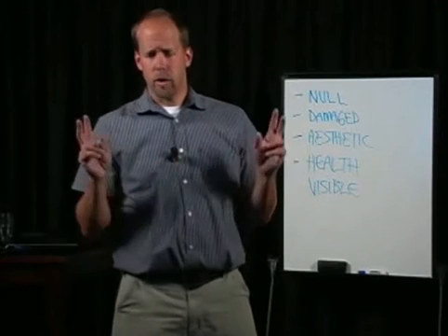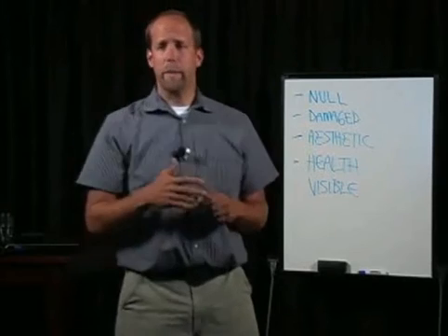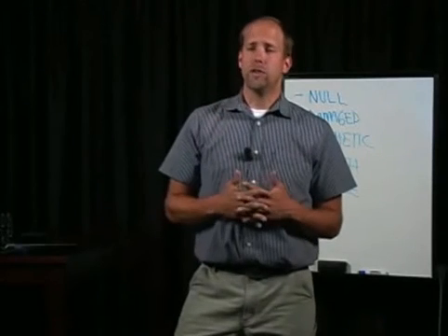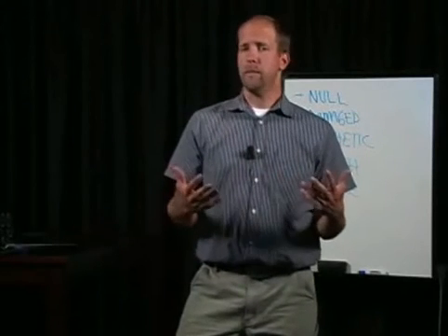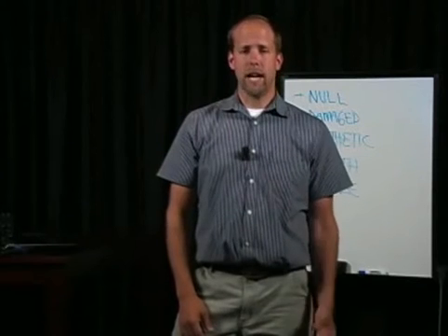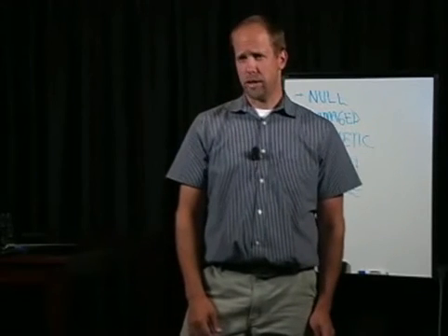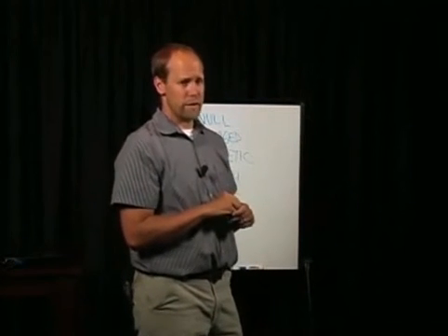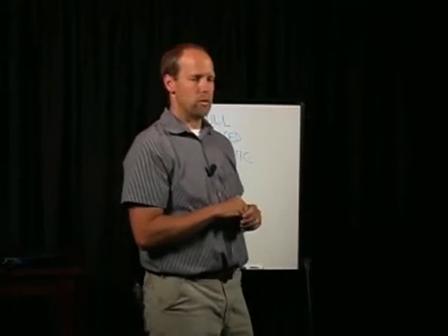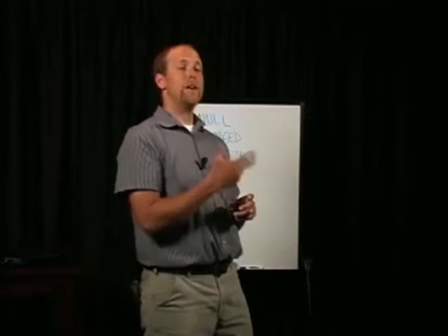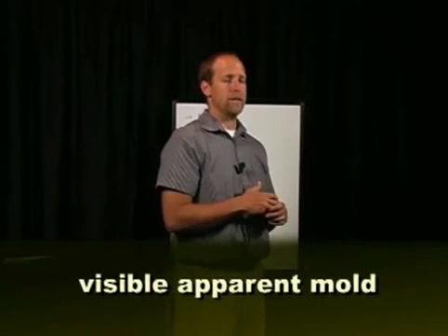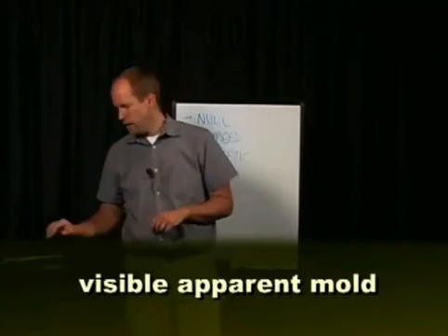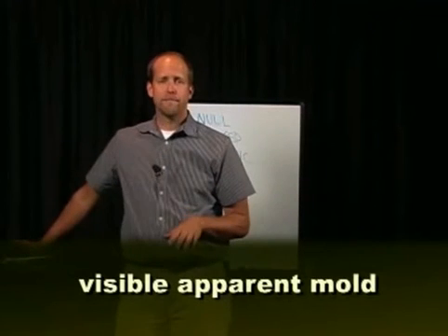The term visible mold applies to what appears only on the surface, not to what is borne out by professional examination, scientific sampling, and confirmation by laboratory analysis. The term visible mold should not be used in reference to actual mold growth. The term visible apparent mold is accurate, the word apparent. Don't guess.